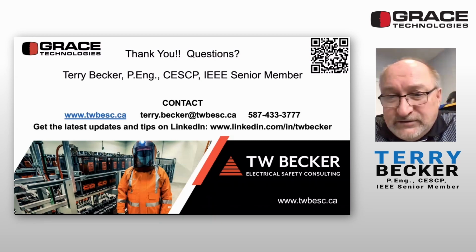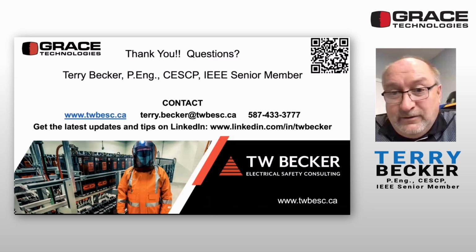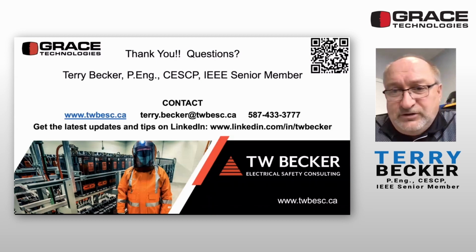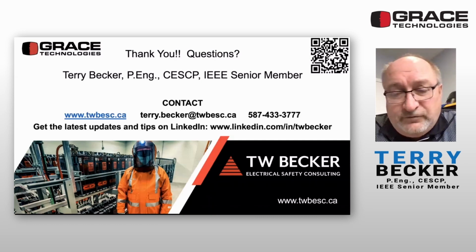Is high potential testing considered energized work? Well, using any test instrument is energized work, but not using high pots. For instance, there's a shock hazard there. You should be trained and instructed and follow procedure using that test instrument, but you don't need arc flash and shock PPE to use it, right? So that's specialized test instruments. Get trained on that test instrument, get trained on how you're supposed to use it. You don't need arc flash and shock PPE to be using these test instruments.